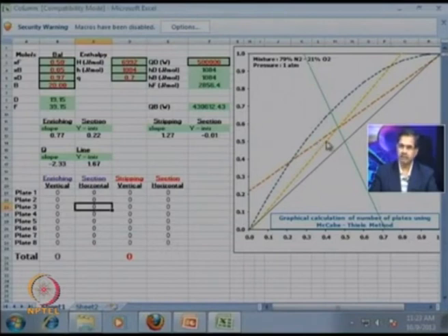The fourth line, rather curve, is also very important, which is the equilibrium curve, and the data is known to us. This data is known for 1 atmosphere for such a mixture. I have y and x known to me from distribution coefficients and things like that. This is standard data. I will know these equilibrium points, and therefore, I can plot this curve on this graph.